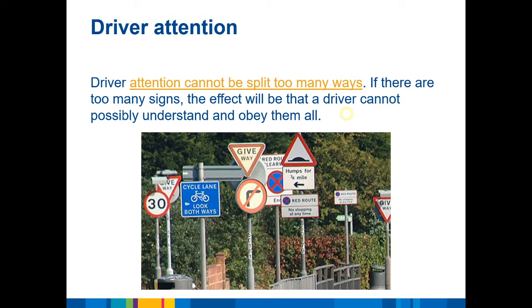And the same thing is true of the green directional signs that are around the state. They have minimum lettering heights so that they are visible from 100 meters away or 150 meters away, depending upon the speed limit. So on the freeway, the letters are 300, 400 millimeters high in some cases. They're really quite big. And on local roads, they're much smaller because you can read them at a much more comfortable speed and a more comfortable distance.